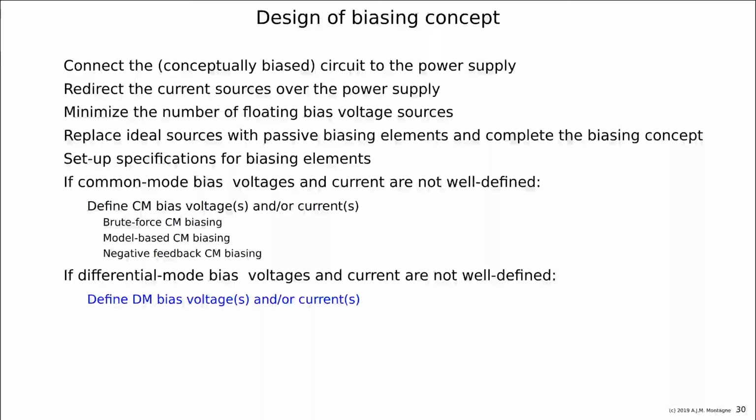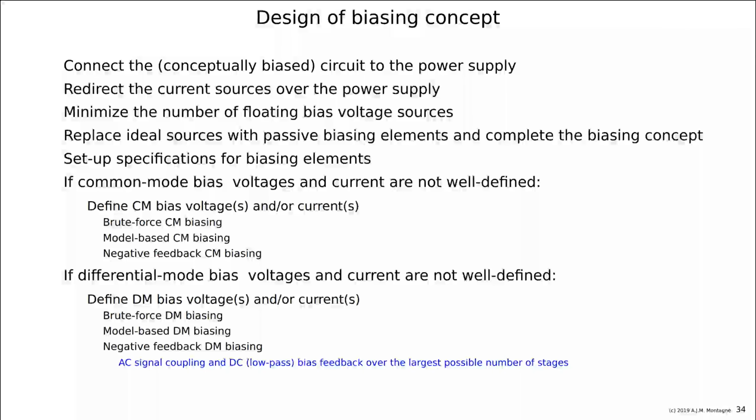The same we can say for differential mode. If differential mode voltages and currents are not well defined, we have the same methods. We have to define them, and we can do brute force, model-based, and negative feedback. But at the end, we have a little bit more techniques available. Well, we also have them for common mode, but we seldom apply them because that's not necessary. We can do auto zero and AC coupling and negative feedback biasing in this way. So let's go through the steps and do some examples.